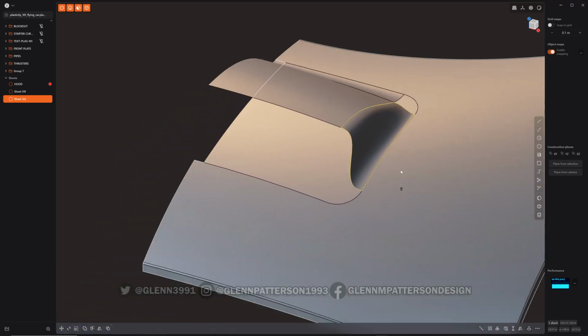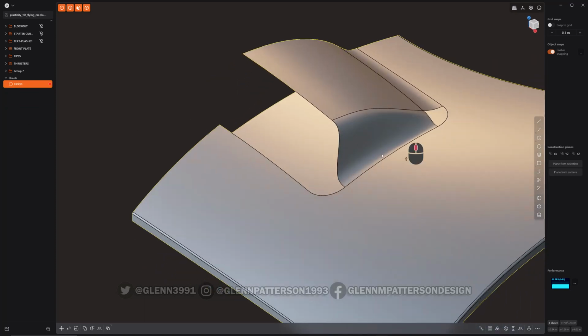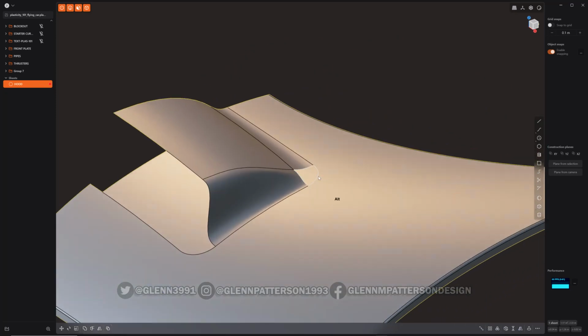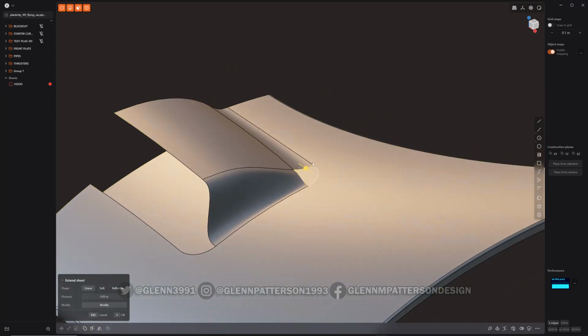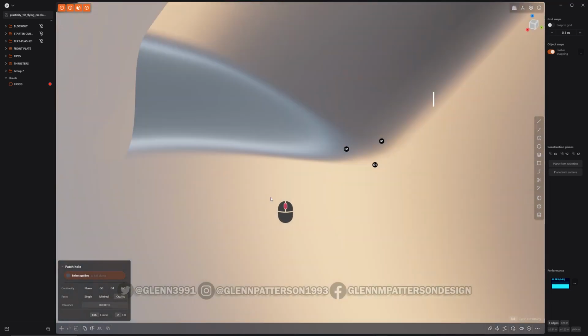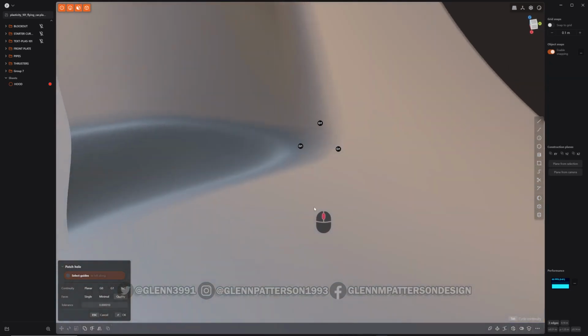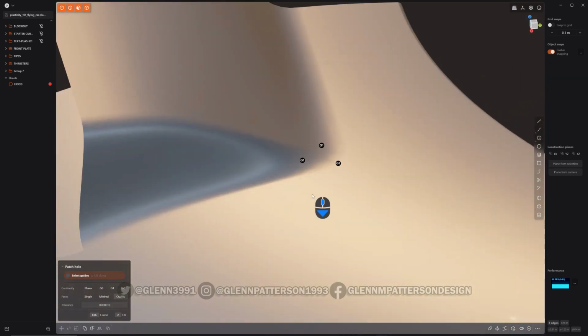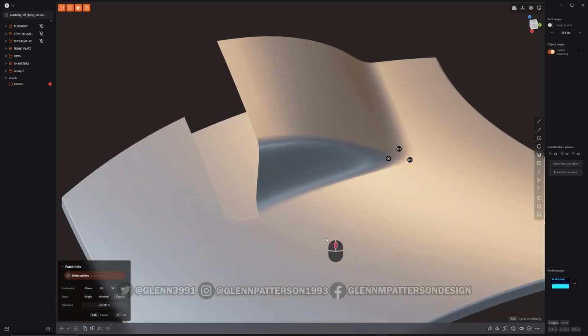All right. So let's go ahead and take our first shape, our hood, and then select everybody and join. There we go. It welded everything together. So now I can take, if I hold down Alt, it'll hit that boundary edge right there. And now I can just run my patch, which is right here, but hotkey, right? And then smooth it to G1. And as you can see, it's super smooth. So it should render pretty nicely in whatever renderer you're using.